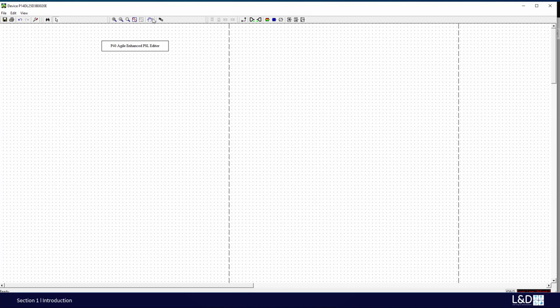So here, the pan is used for moving the icons on the canvas, and the link is to connect the different inputs and outputs to the logic gate, etc. And some functions can also be accessible when you right-click a mouse. You can choose to set the grid function, for example, and the zoom in function, and you can choose zoom to fit.